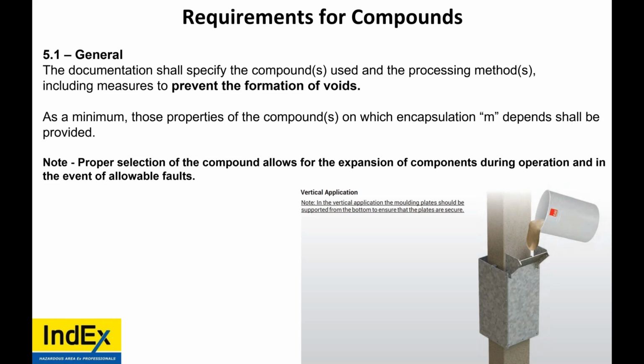So there's a lot of testing and other requirements done at the manufacturing and design stage before they send it to an ExTL testing laboratory, and it's either approved or disapproved by the testing laboratory, which would then, once it is approved by the ExCB, certification body, or ExNB, notified body. When they are approved, that information has to be in the certificate and in the manufacturer's IOMs, the manufacturer's manuals.